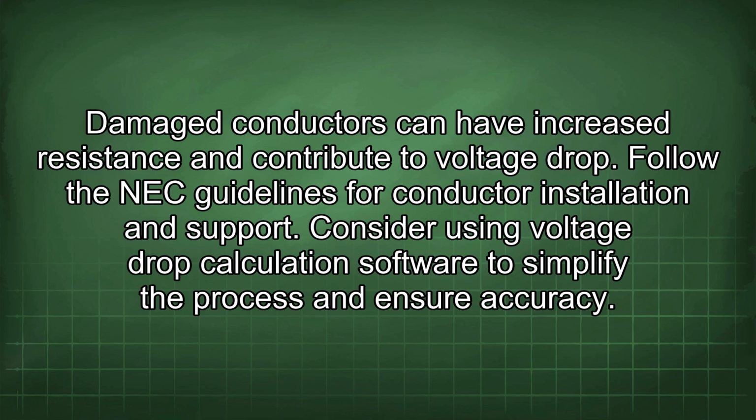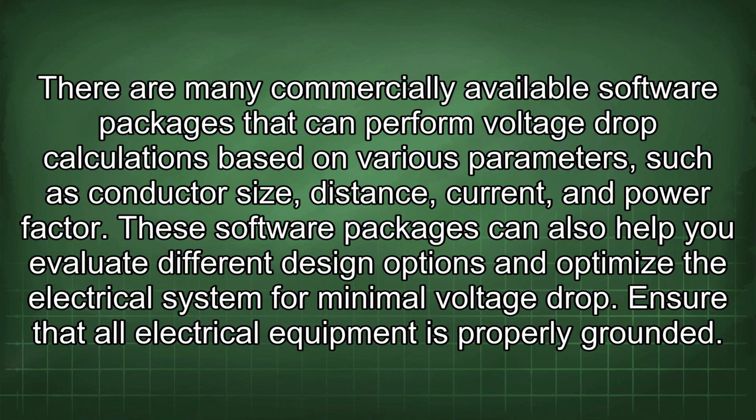Consider using voltage drop calculation software to simplify the process and ensure accuracy. There are many commercially available software packages that can perform voltage drop calculations based on various parameters, such as conductor size, distance, current, and power factor. These software packages can also help you evaluate different design options and optimize the electrical system for minimal voltage drop.